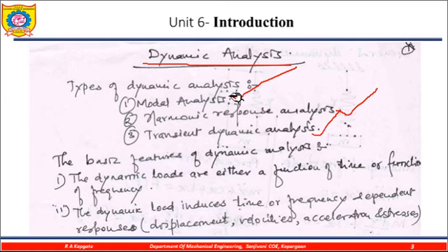The basic feature of dynamic analysis is that the dynamic loads are either a function of time or a function of frequency. Whenever loads are applied on a structure, component or part, it is a function of time. If the load is applied with respect to time, it is not gradually increasing or changing, but impacting like this.